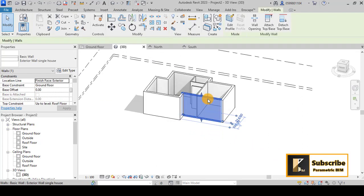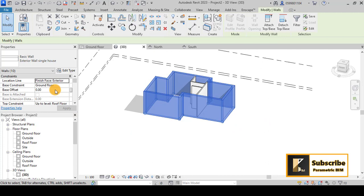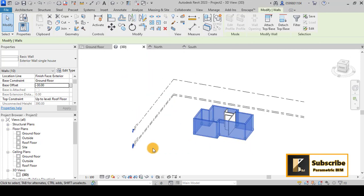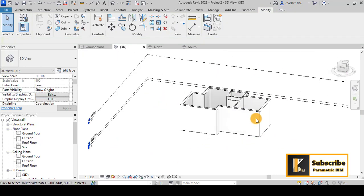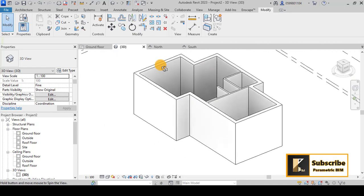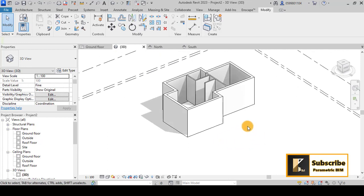Maybe you can select this one and also select all instances visible in a view, and in that case I will go for the base constraint or the base offset with minus 30 because the walls must be extended to the exterior level or the outside level. Also for the interior, maybe you can do that, but we do not have to do that for the interior, just for the exterior. Okay, now we are done with the walls and the levels.